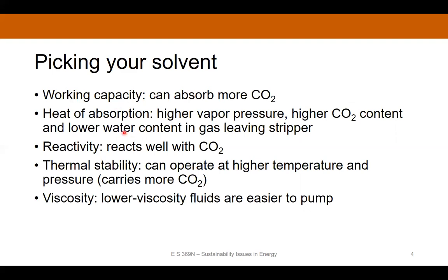So basically, you have to remember that absorption releases heat, and so we'll be operating at a higher vapor pressure, and we'll be able to purify the CO2 more easily. We obviously want the solvent to react well with CO2. We want it to be able to capture that CO2. And we want good thermal stability.